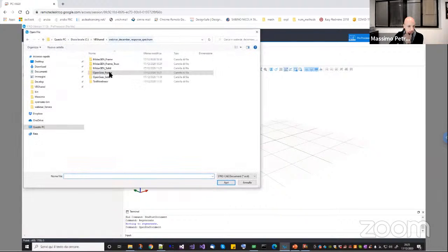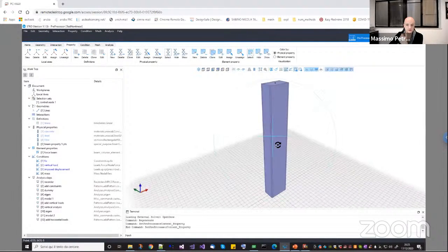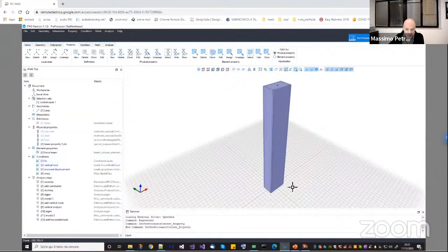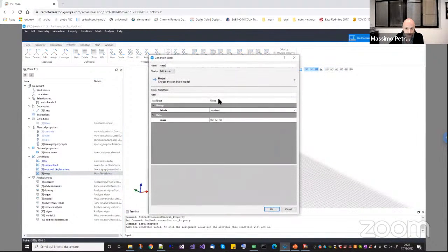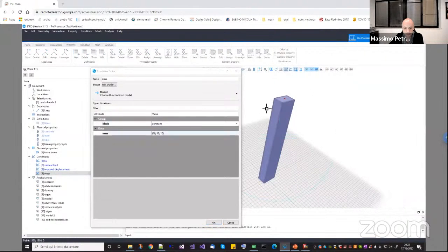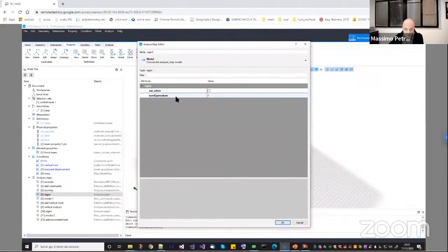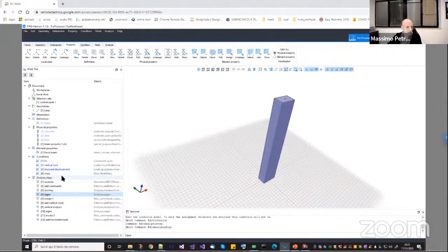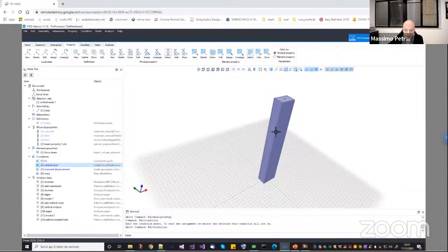Now, if I go in test nonlinear, this is a very simple column, okay? You have a fix at the base. So this is basically a simple cantilever. And I'm just using a simple mass applied here on the top in the 3 directions. I'm asking just for a single mode, okay? And this is quite interesting because I'm using a certain vertical load that makes my structure go a little bit into a nonlinear stage, okay?